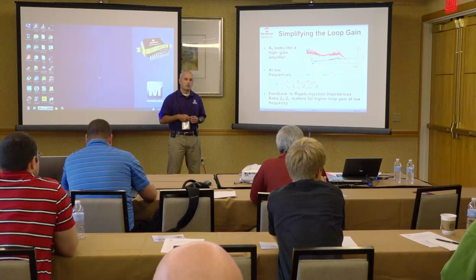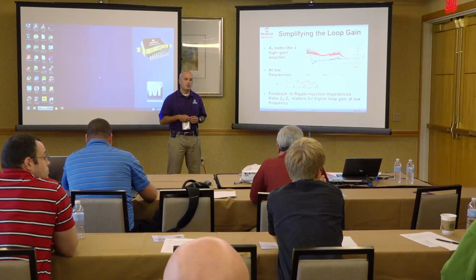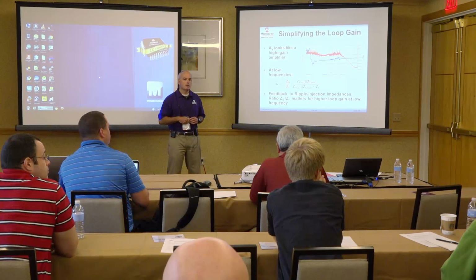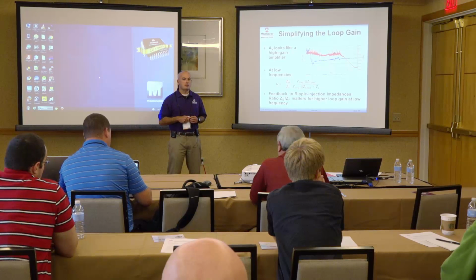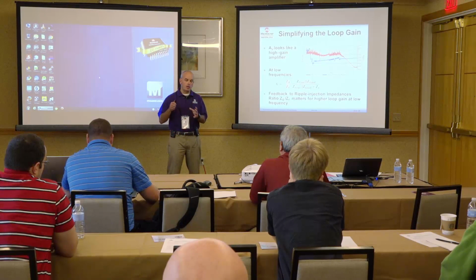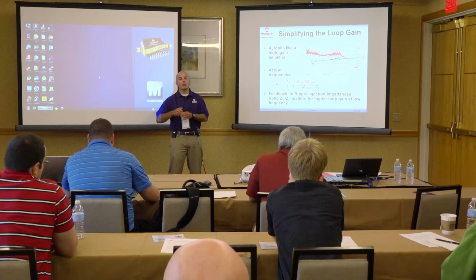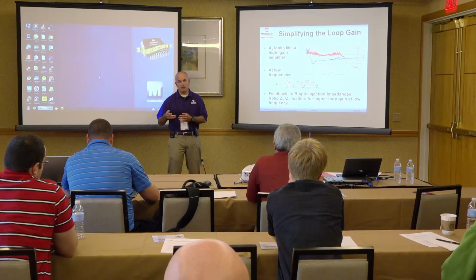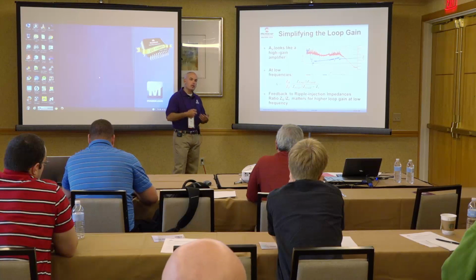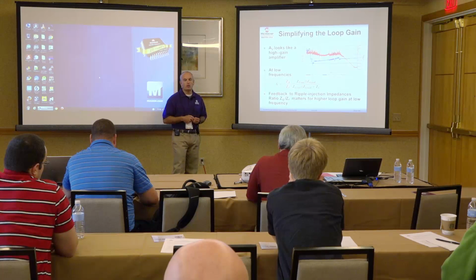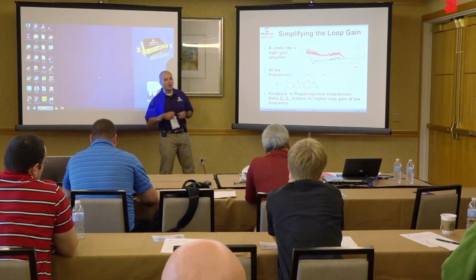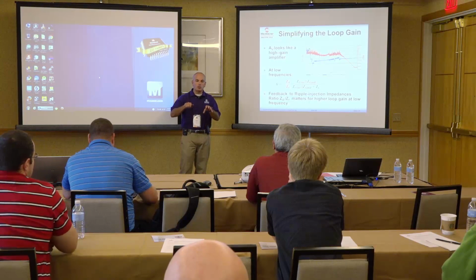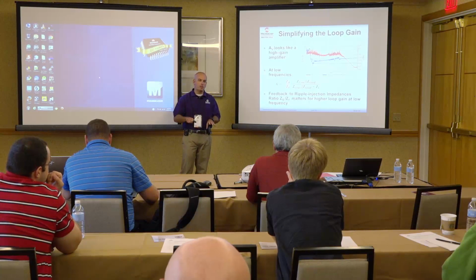the transient response, yes, if you have enough ESR. So the more ripple injection you are injecting, you need to inject a minimum for stability, but the more you inject, the more it will degrade your low transient response. So if possible, always try to live with the minimum.